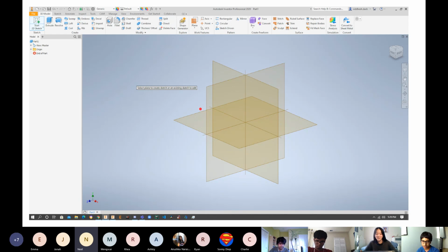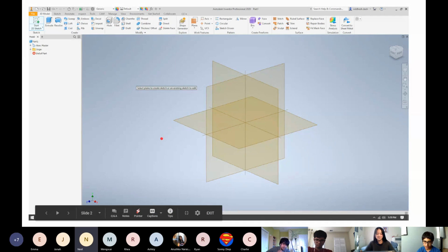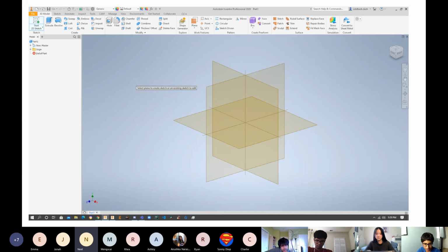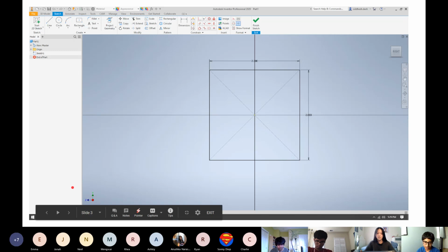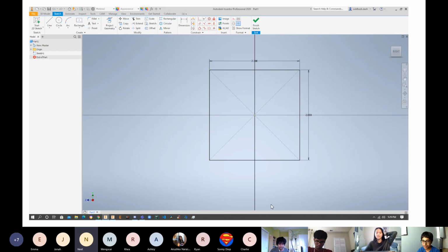So if you have this from the front of your robot to the back, you would want to create it using your center. If you could tap on that screen, that would be nice. So you want to orient it such that when you actually create the part, you don't have to reorient it in your assembly. Again, it just makes it easier when you have to install a new version of that part into the assembly. It's a whole lot less work once we get there. And we'll explain why this is important in a future workshop, because that's not really something for this one.